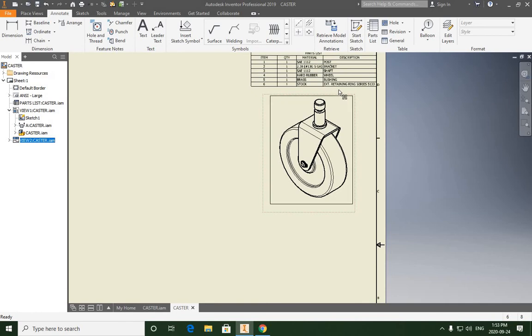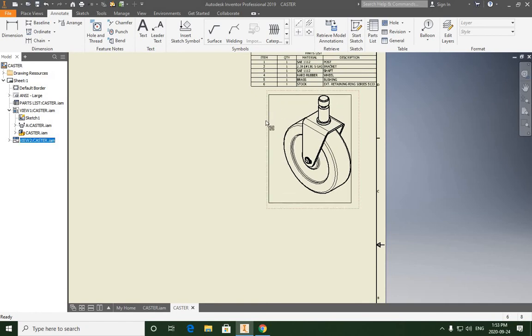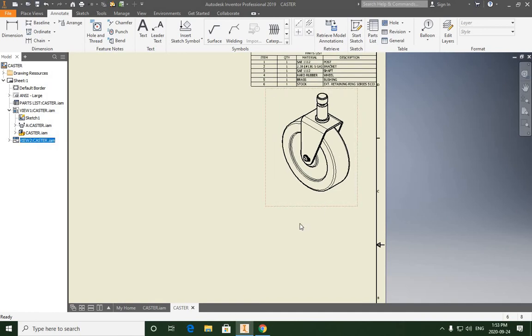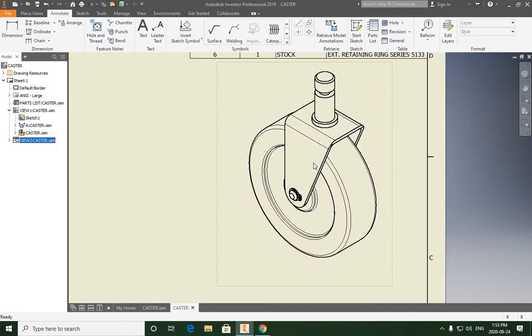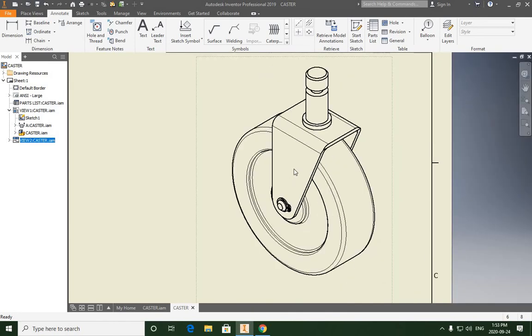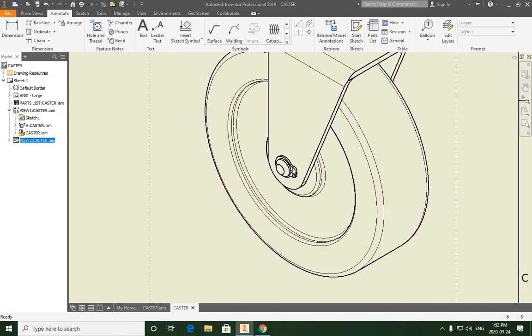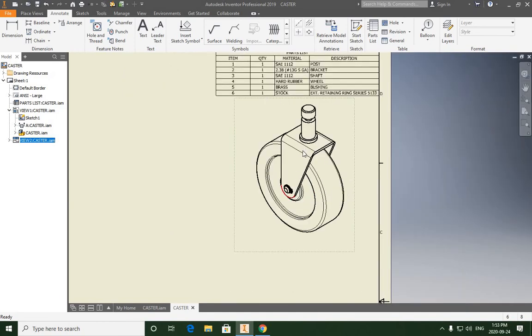Now it's customary to throw isometric views in the top right-hand corner, depending on any software you're using. Why not do this? It's a bonus for anybody who's building the part. They can get an isometric view of how it's supposed to look. And this is the best view to show because it shows our retaining clip in place as well. So we don't want to have the hidden details on for this, because it's going to look too distorted, right? This is basically just what we see in object line.